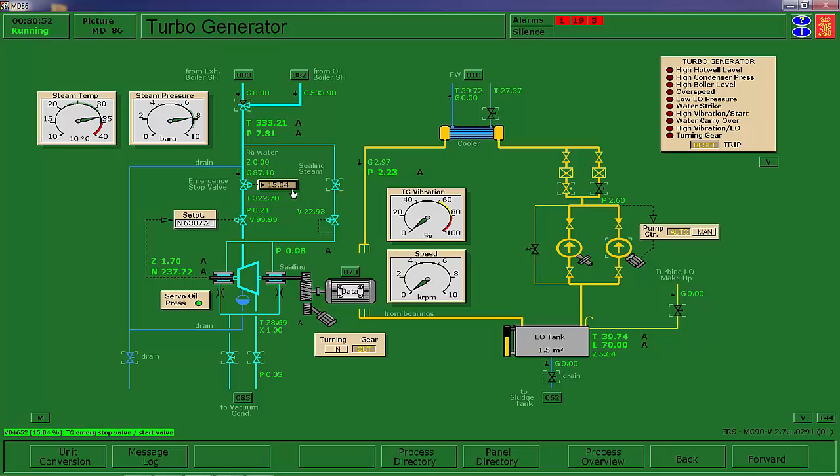Here I'm opening it at 15%. That's not realistic. Maybe there's some slop in the valve. But the other one is once it's started, it doesn't come up quickly. Normally what you do is you just crack the throttle until you see the steam turbine output shaft to the generator. As soon as you start barely seeing that move, you just step back, and over about 5 minutes, it'll slowly come up to speed. Again, it only takes 1 horsepower to bring this up, and I've got over 900 horsepower available.